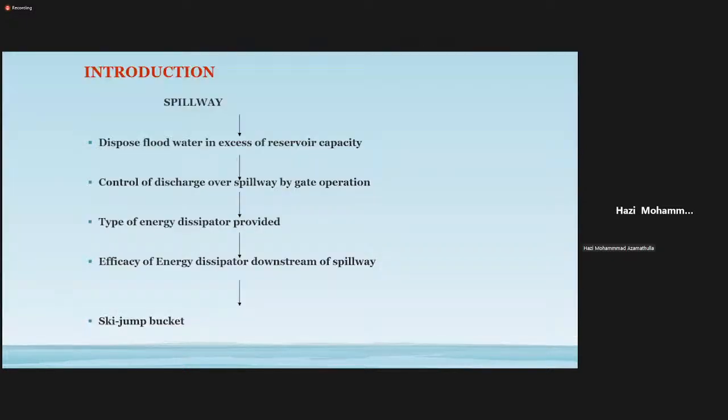Yes, spillway means spillway. Just now we discussed the non-overflow section; a spillway means you need to pass the flood water in excess of reservoir capacity, to dispose of the excess floodwater safely. So you have to control it through gate operations, and also you need to provide an energy dissipator on the downstream side. Okay, so here, as I told, a ski jump bucket or trajectory bucket or flip bucket. Different countries have different names, but the concept and purpose are the same. Okay, next slide please.